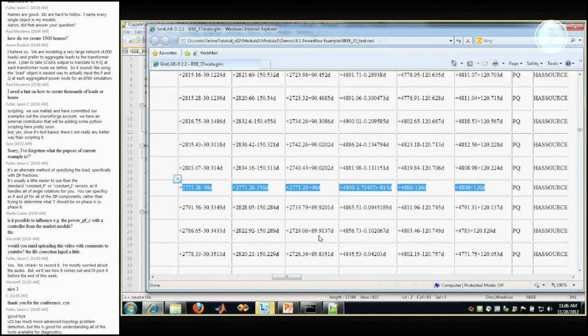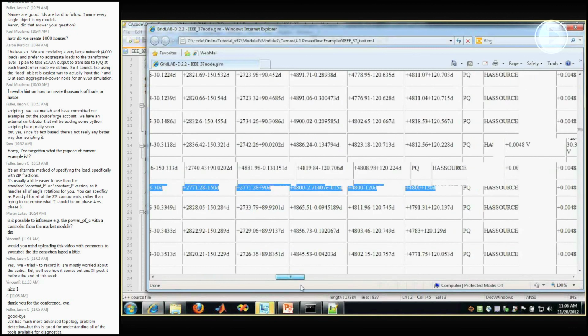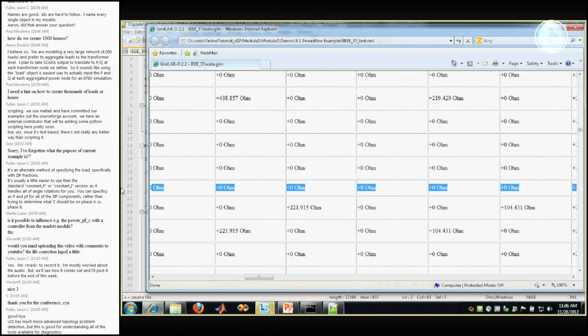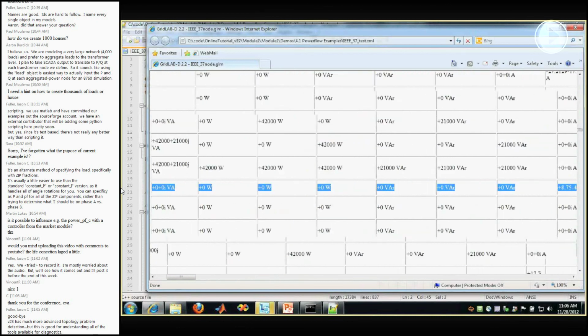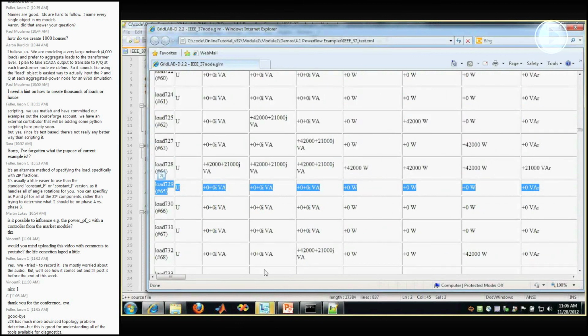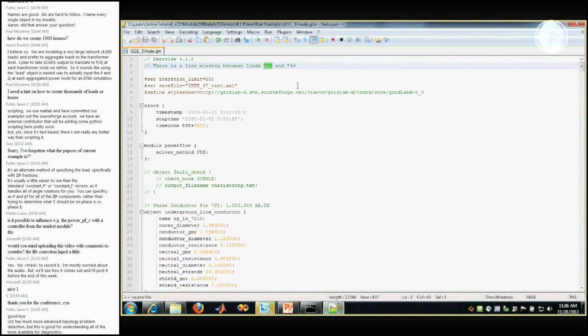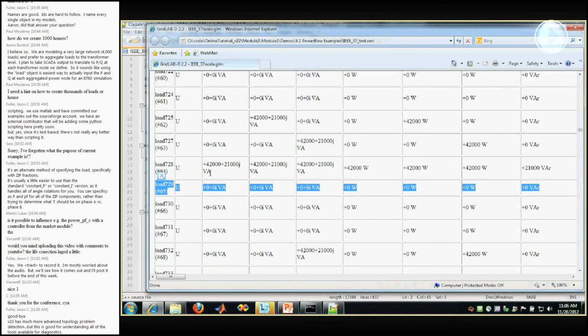So if we go over here and look, this is going to be kind of hard to do. We find out this should be like node 744 or 729. Is that the right one? Okay, 729. So that's the other side of the connection point. Without that connected, forward backsweep is basically assuming this is a new swing node and it's resetting. So you'll still get a valid solution out of this, but it's not really the solution to the system you wanted. So that's something to be careful of between forward backsweep and Newton-Raphson.